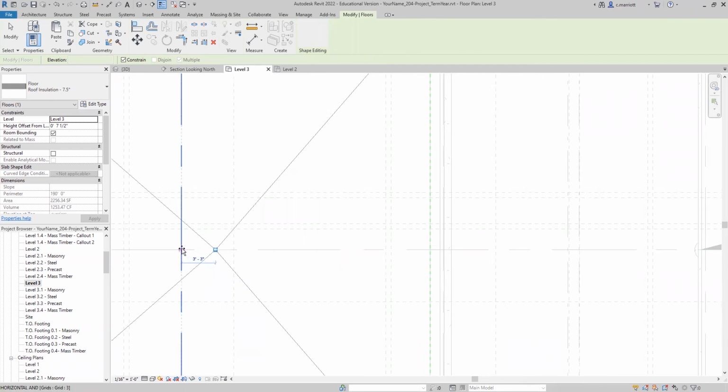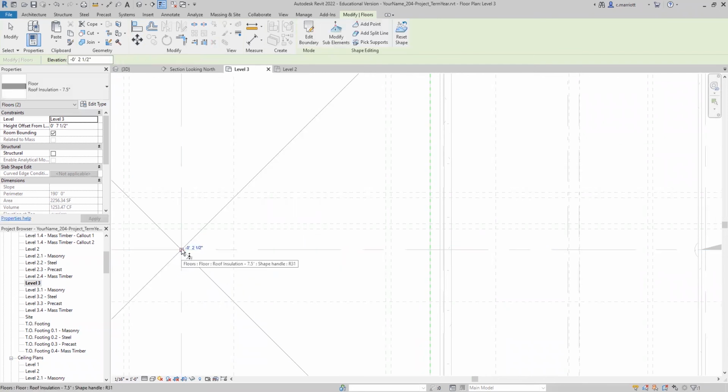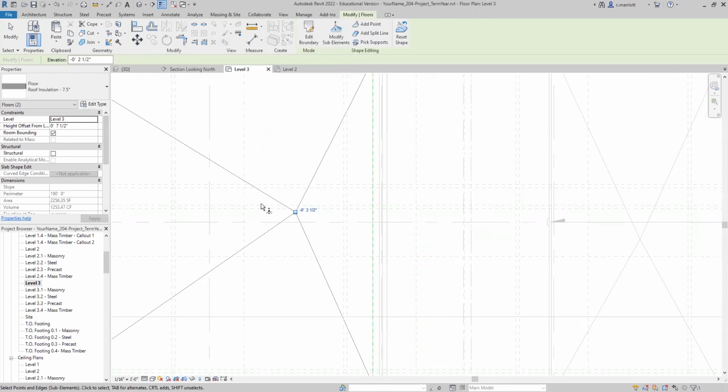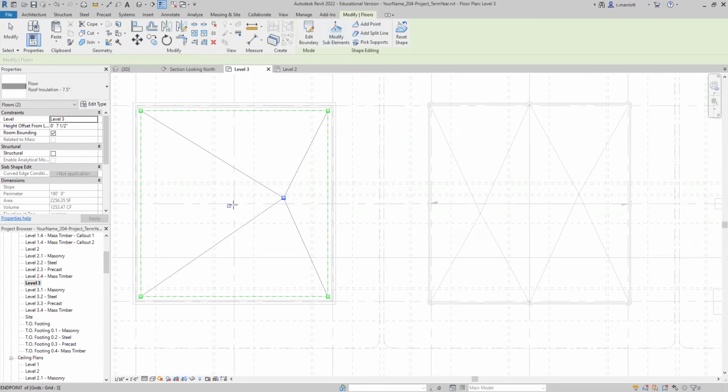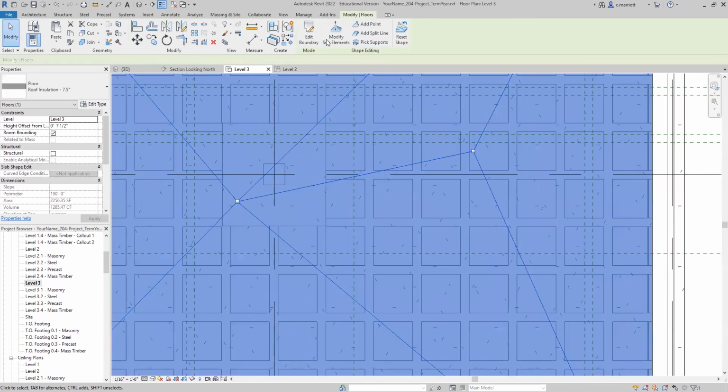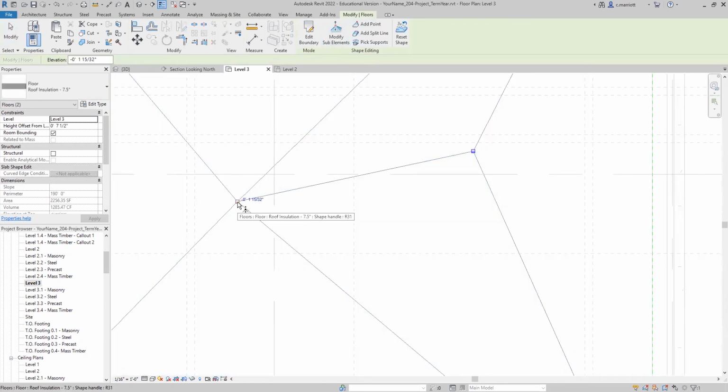Not sure why it wouldn't let me place it directly. And now what I'll do is keep moving it to the position that I want it to. So 12.5 feet. And let's move it up 1 foot 5 and 5/8, same thing as 5.625. And I'll add another one, presuming it's not going to let me put it where I want to. So let's edit, modify sub-elements, put it at the same height, minus 2.5 inches.